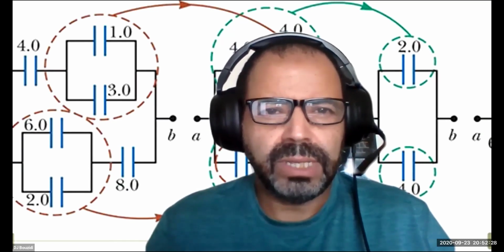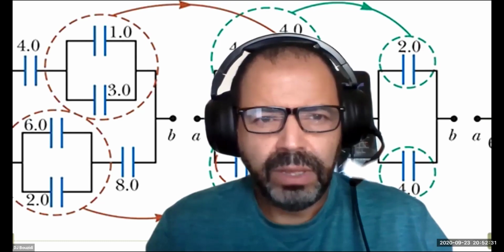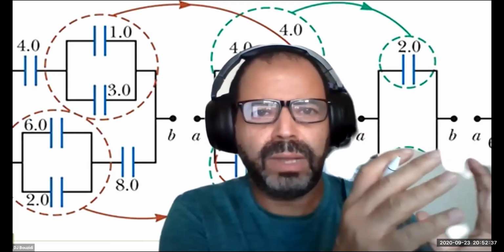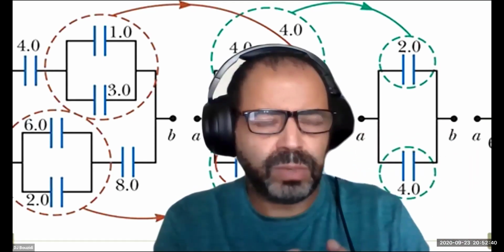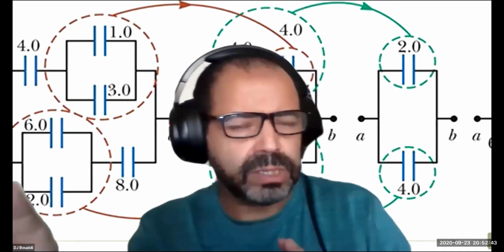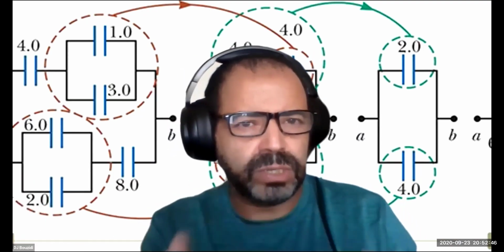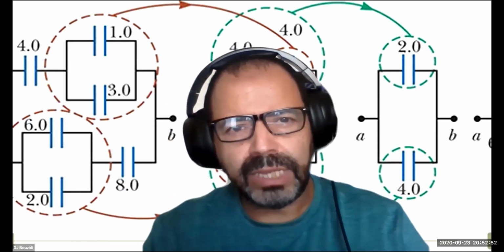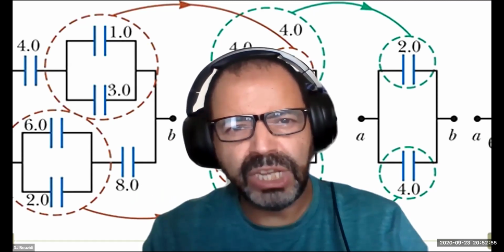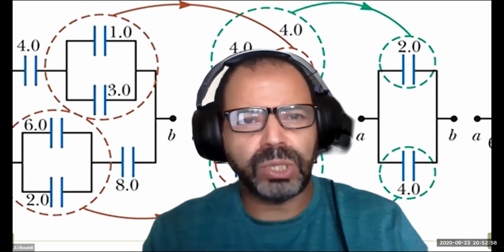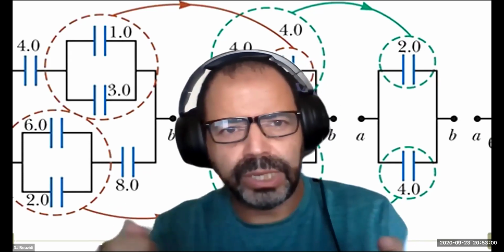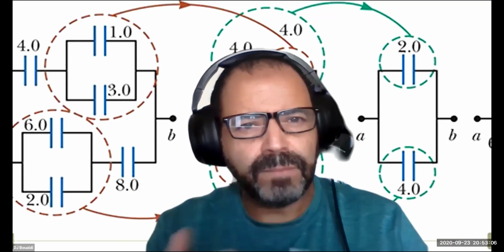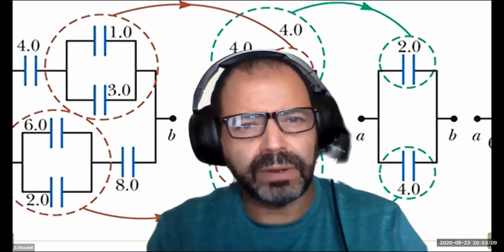Part of the discussion, I already hinted at it, is the fact that 966 microcoulombs was split. Part of it went to the 644, so I know the difference has gone to C1. I can actually calculate the difference in here and say this is how much went to C1, and apparently that one is split between the other two. So that's basically how much it is. If I am curious to find how much energy was taken from the whole battery, then it's another story. Then I'm going to calculate all the energies, or at least with the C equivalent, and find that it should be equal to the C equivalent. So that's really part of the discussion that I should have in here, okay?